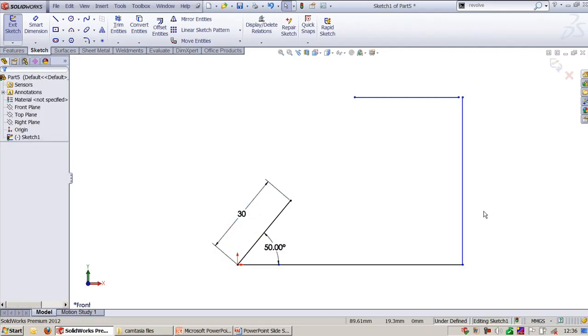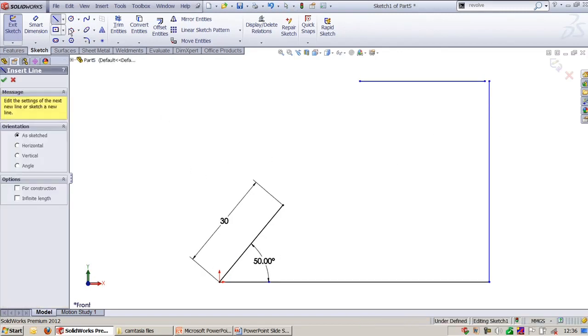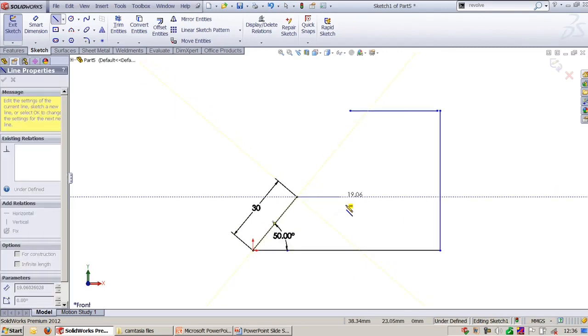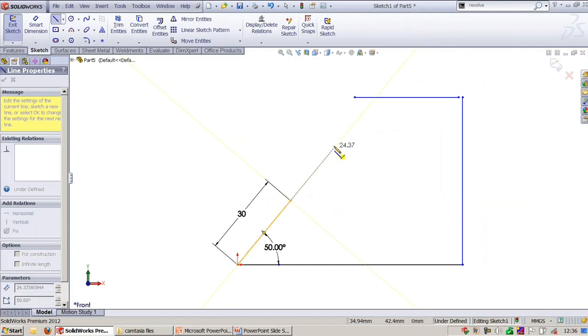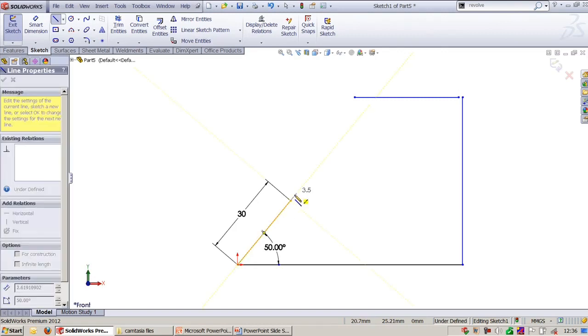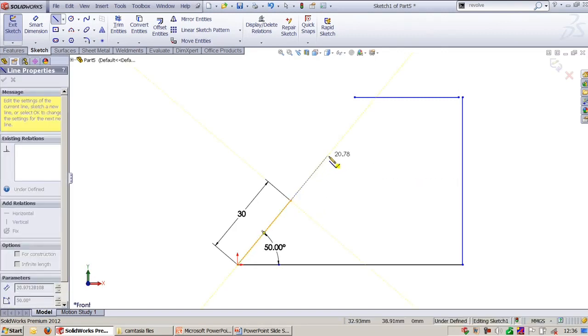Now this is the sketch created using line segments. But once you are creating a line, you also have the advantage I mentioned, inferencing. That means I want to create a line. You can see here it shows a yellow color line which is called inferencing. You can draw parallel to this, or I'm sorry, the line command is followed with the arc command. If you want to switch this, I can select A, and now you can see once again it is switched back to the line command.